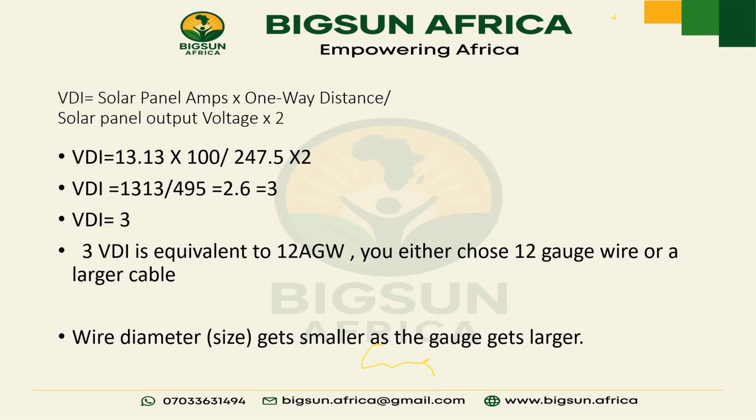Please, a question. It is a bit confusing. What are we multiplying by 2? Is it the total voltage, the total solar panel voltage? Then you are multiplying it by 2. That is the formula. So this equation is as good as saying the solar panel amps times the distance of the panel to the charge controller, then all divided by voltage times 2, right? Yes, total voltage times 2.